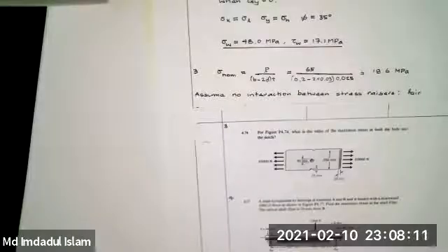I mean, you could go look. Why am I picking that? I can't do it in my head, but I think it's certainly less than a 5% effect, so it's satisfactory. I think it's more like 1 or 2. And so to give you a definitive rule, at 3 diameters center to center, you don't worry about interaction. But you could start doing what you were saying when it got closer than that. It would be a way of trying to allow for interaction.